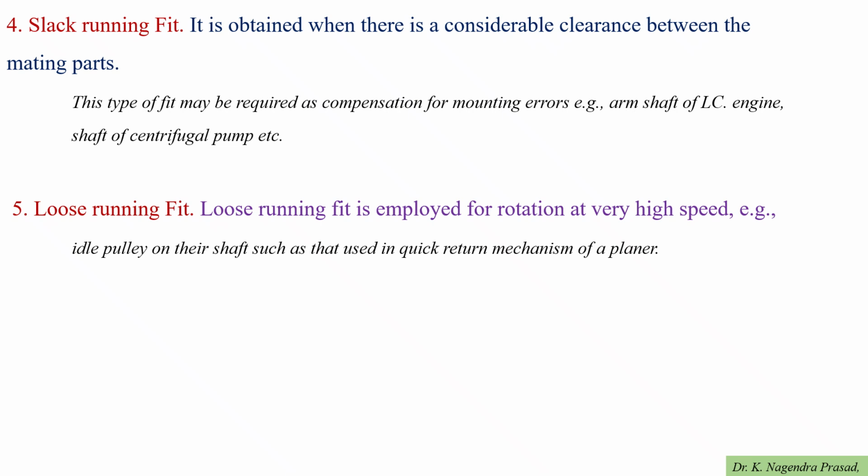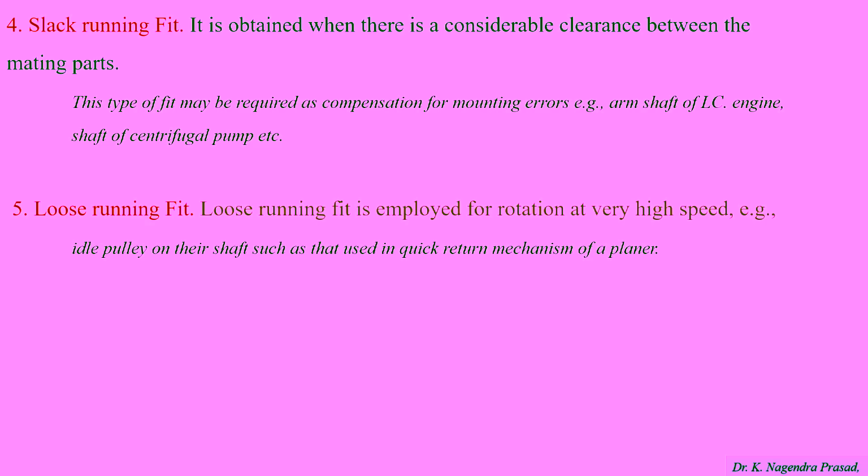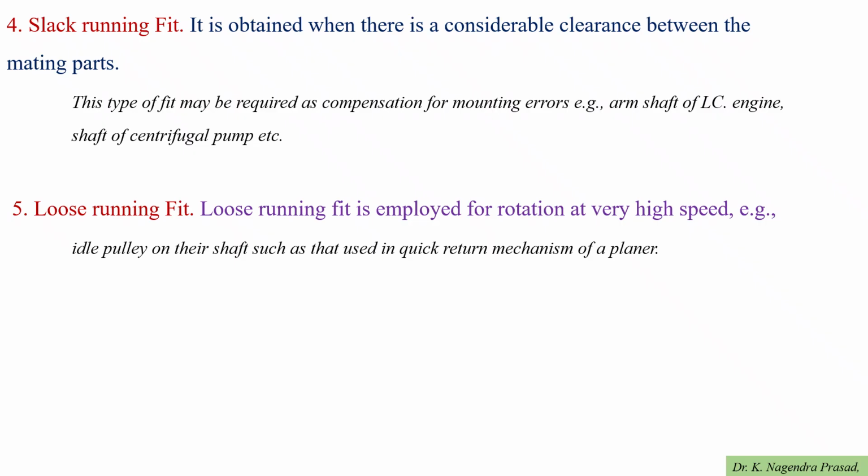The last one we have to see in the clearance fit is the loose running fit. Loose running fit is employed for rotation at very high speed. Let's take the example of idler pulleys on their shaft, such as those used in the quick return mechanism of a planer.